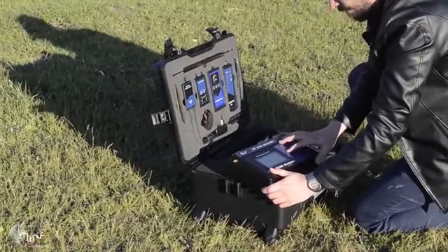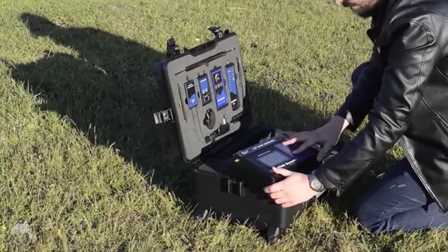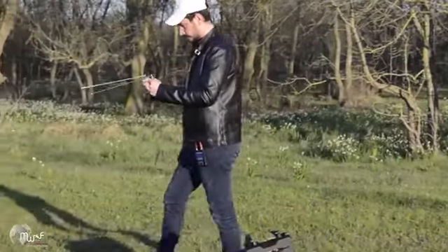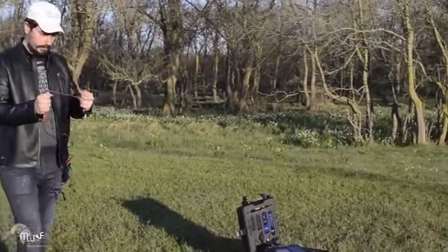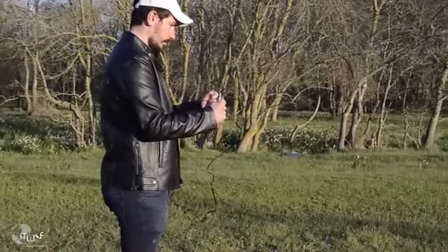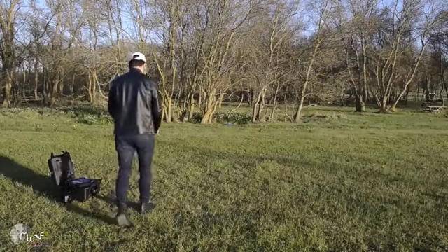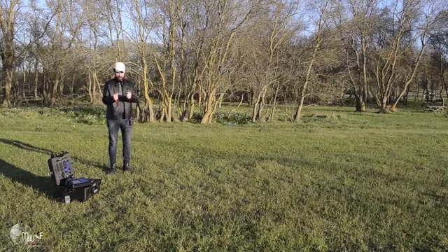Choose the line tracker system from the main unit and assemble the contents of the system as we saw earlier. Then install the receiver on the belt or put it in the pocket. Hold the antennas horizontally, maintaining their balance and spacing between them of about 30 cm. Then start walking circularly around the ground transmitter unit that is planted on the ground. Stop at the intersection of the antennas, then move away and change the direction of walking to make sure of the cross point,